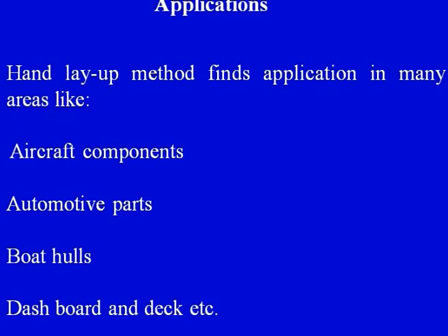Now, the applications of hand layup process are aircraft. In some aircraft components it can be used, and automotive parts can be made by the hand layup process. Boat hulls is one of the most historical applications of the hand layup process. Dashboards and decks can also be made by the hand layup process. So this is one of the most easily and widely used processes of making composite parts.